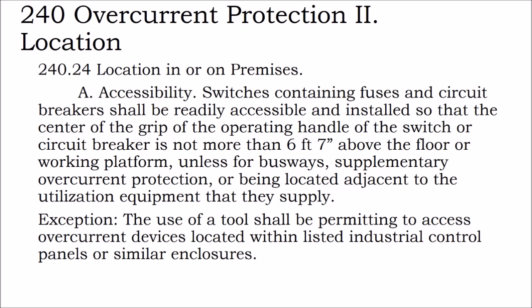Switches containing fuses and circuit breakers shall be readily accessible, installed such that the center of the grip of the operating handle of the switch or circuit breaker is not more than 6 foot 7 inches above the floor or working platform, unless for busways, supplementary overcurrent protection, or being located adjacent to the utilization equipment they supply. Exception, the use of a tool shall be permitted to access overcurrent devices within listed industrial control panels or similar enclosures.